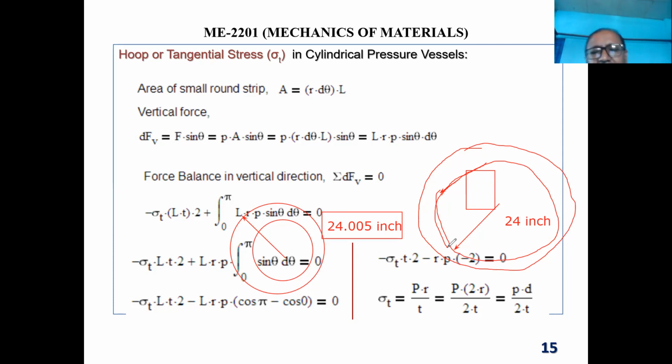You have two options. You can hammer it a little bit, but if you hammer, then there will be micro crack developed right over here. You might not see it with your eye, or it might show as a crack in the outer. Okay. So you have other option that you can heat the outer cylinder, warm up. If warm up, dimension increase, then radius will be, diameter will be increased a little bit. Then you put this one inside, then you just cool down to room temperature. Then what will happen?